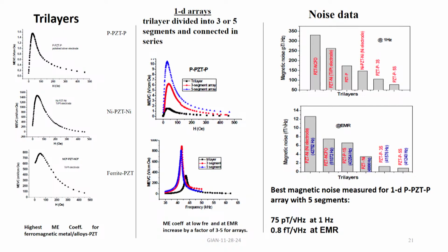So, now if you want to use it for magnetocardiography, the signal that is produced is 20 picotesla, and it is not sensitive for 20 picotesla, it is only 300 or above that value, it is no good.